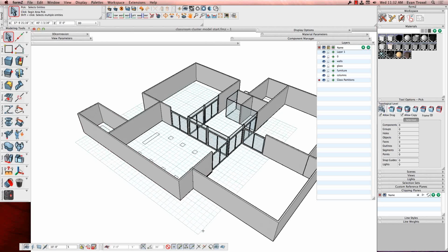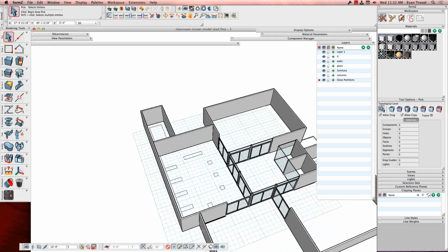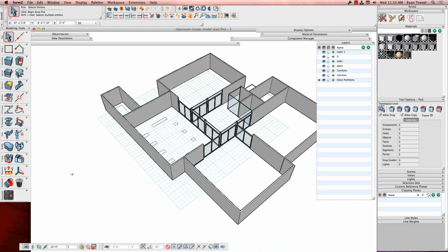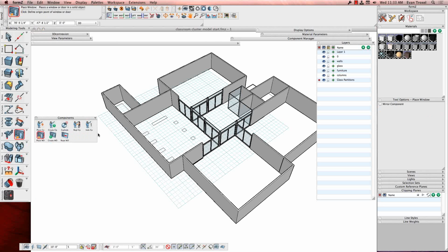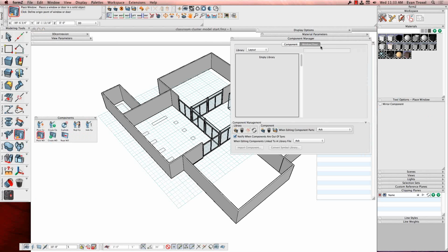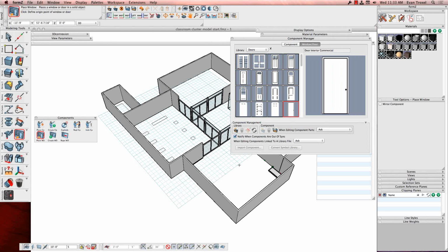All right, so what we've got now, let's see. Let's go ahead and draw a bunch of cabinets. And again, I'm just going to use the wall tool for that. Actually, no, let's do doors first. So one of the architect-friendly tools in here is I can place windows and doors, and that's under my components because it actually comes with a whole window, door, component section here. So I'm just going to place some very simple doors.